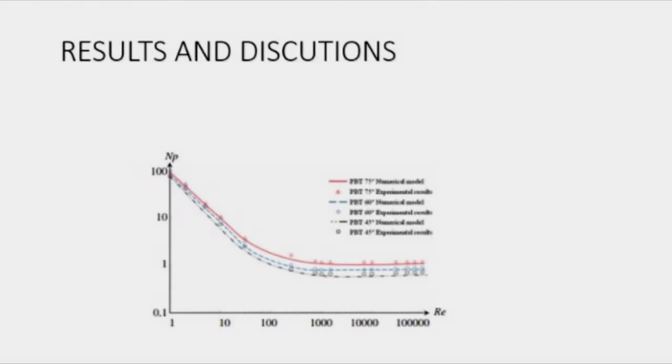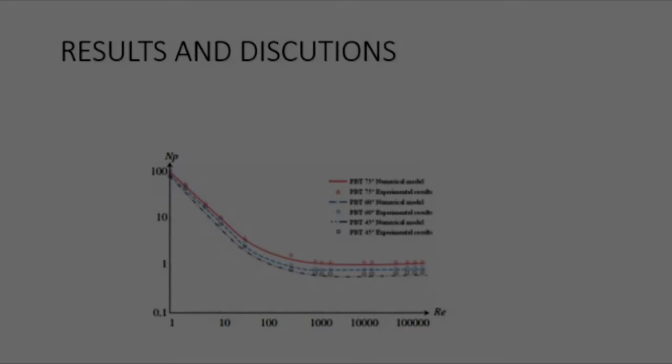When the power number obtained in simulation was compared to the one obtained in the paper, which compared the same type of impeller, changing the blade angles from 45 to 60 and 75, we can see that it behaves similarly, and that by augmenting this angle there's a greater energy transfer to the fluid, so this could be a way to optimize the new impeller.